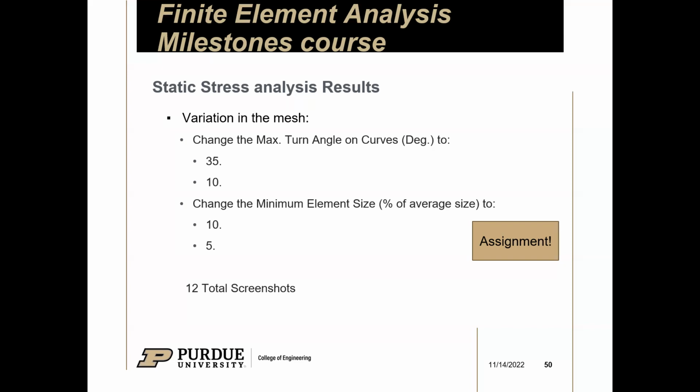Okay, so if I decrease the max angle, then it's going to compile faster? Yeah, to give you a more accurate result, it will probably take a little bit more time because you're fitting more triangles in the mesh. Each one of those takes a little bit longer to calculate, but it will be more accurate. And obviously you might not want to waste time analyzing a bigger part in certain places where it just drops. So you can ignore that area and focus on the important regions. Okay, so you're going to change that to 10.